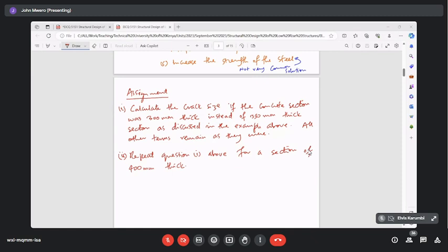The 30,000 is usually a measured stress-strain relationship for concrete. The 30,000 is usually laboratory measured. And for laboratory measured test setups, you cannot set the test to run for 10 years. So it's generally referred to as a short-term Young's modulus of elasticity of concrete. What we need to use is a long-term Young's modulus of elasticity for the concrete, because the concrete element, like a box culvert, will stay there for many years. So generally, it has been accepted that the long-term modulus of elasticity for concrete is basically about 50% of the short-term modulus of elasticity for concrete. That's why we apply the half.